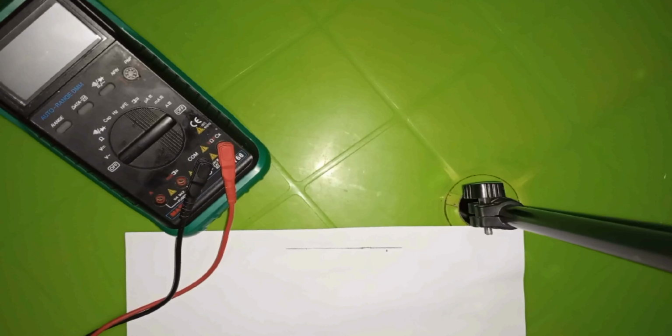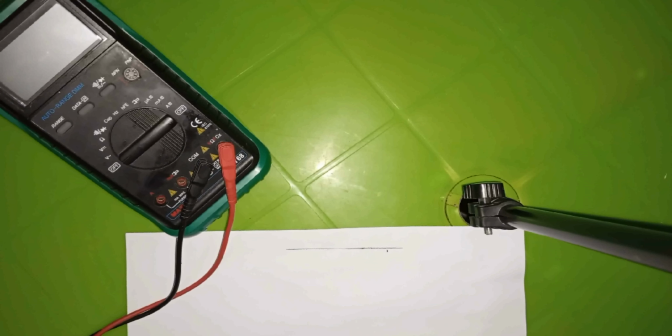Sorry, you can have your resistor in half watts. You can also have your resistor in quarter watts. So resistors can be in half watts, quarter watts, 1 watt, and also 2 watts as the case may be. The watts stands for the amount of power, or the amount of energy, the resistor is capable of dissipating. So when you're dealing with high power applications, you would want to go for a resistor with a higher power rating.